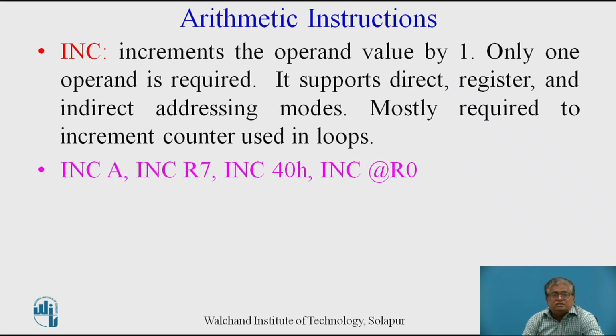The next instruction is the increment instruction, and the mnemonic is INC. It increments the operand value by 1. Only one operand is required, and this instruction supports the direct addressing mode, register addressing mode, and indirect addressing mode. It is mostly required to increment the counter we are using in loops. The format for the increment instruction is INC A.